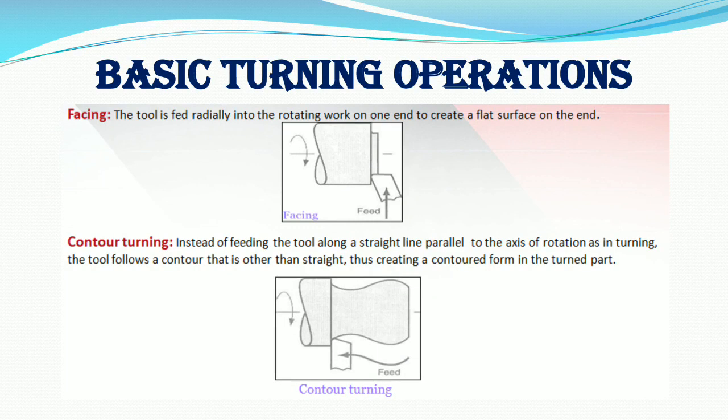Now talk about some basic turning operations. Facing. The tool is fed radially into the rotating work on one end to create a flat surface on the end. There is a picture of facing.